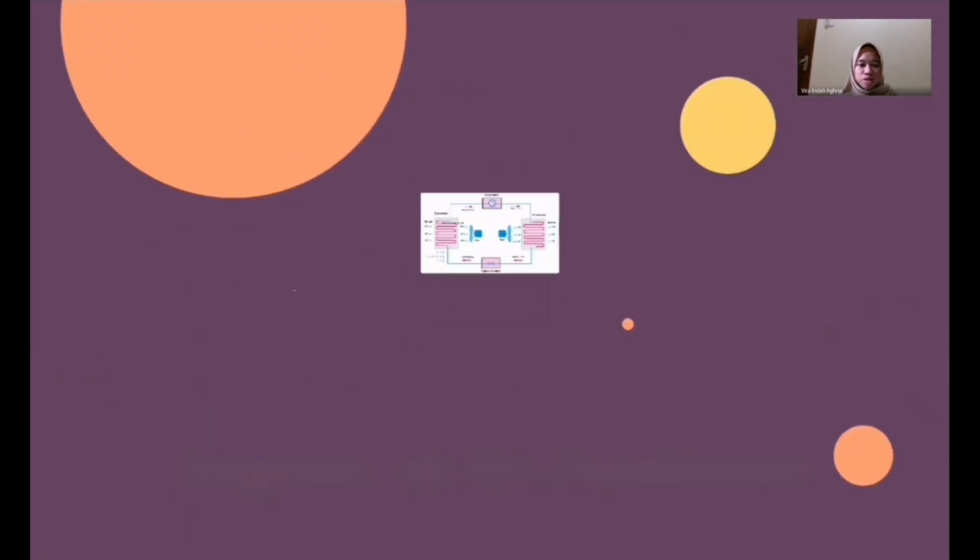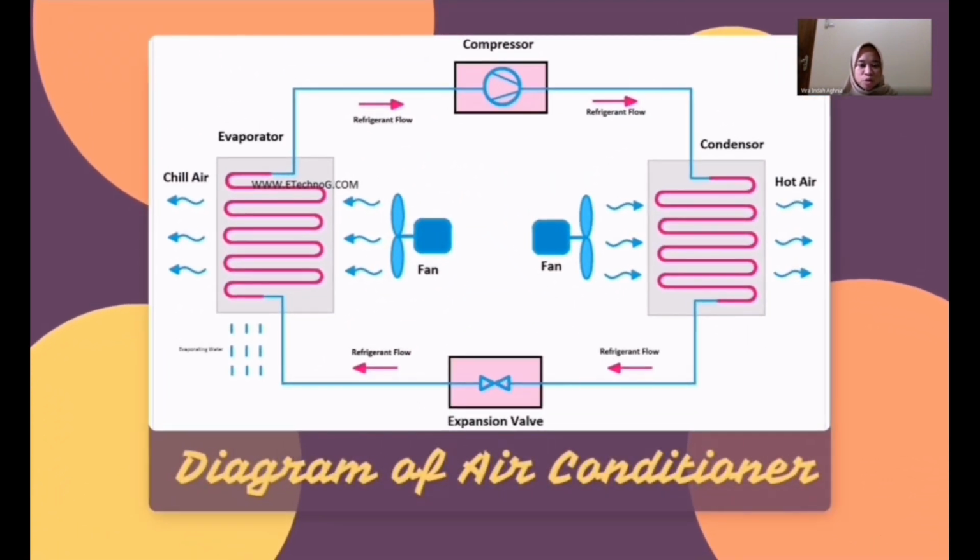There are several components in the air conditioning system including the compressor, condenser coil, evaporator, air handler and blowing unit, and thermostat. The compressor functions together with a substance called working fluid that can easily transform from gas into a liquid. The main task of the compressor is to convert low pressure gas into a high pressure gas which also has high temperature. The condenser coil has a fan fitted into it which cools down the high pressure gas and converts it back into a liquid. The evaporator is located inside the house and it is usually found near the furnace. It is connected to the condenser with a very thin pipe.